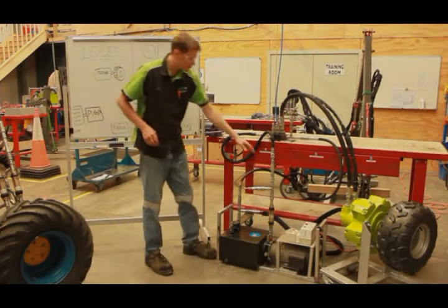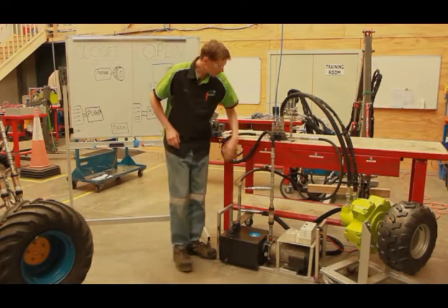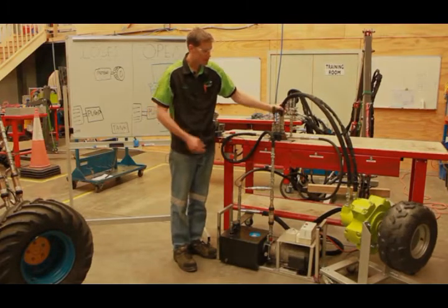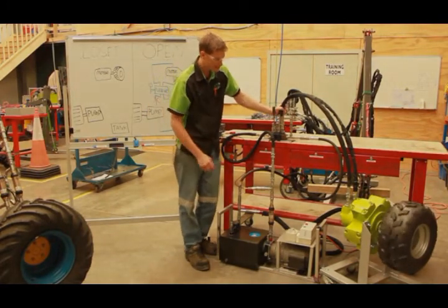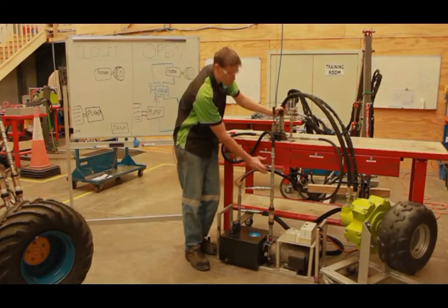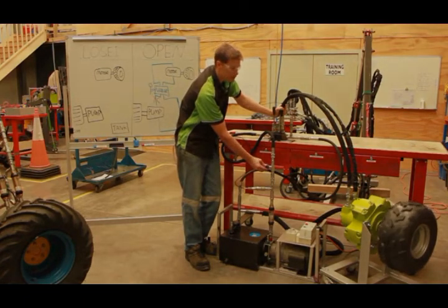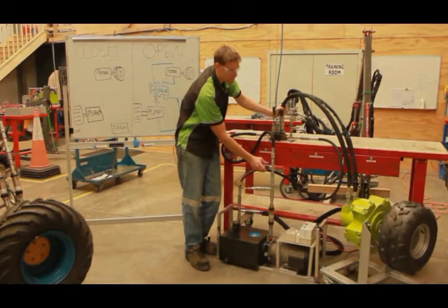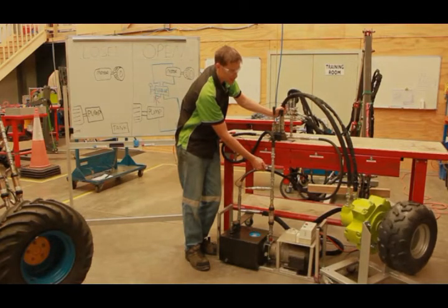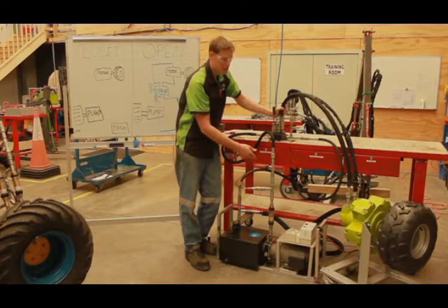And you can see that if I activate my valve, my motor will spin at a certain speed, and I can then start to close off the flow control valve, and it will slow down the hydraulic motor, and in turn slow down the wheel. You can hear when it does that the pump is starting to load up, and my system is starting to create a lot of noise and also a lot of heat.